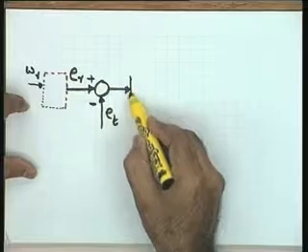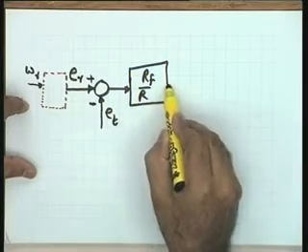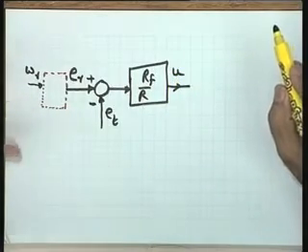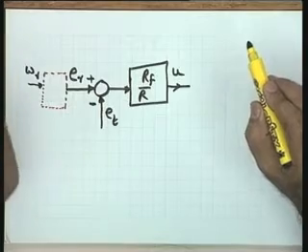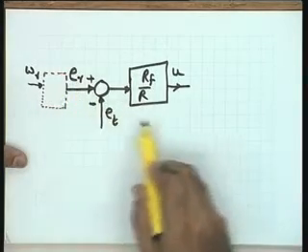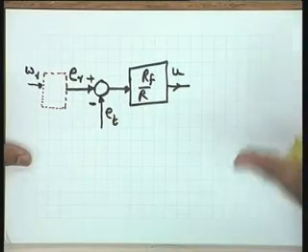So, here I am putting in this particular block an amplifier gain RF by R, and let me say that U is this control variable. So, you will please note the physical relevance, the physical equipment also which is being used to realize the various objectives. Now, U is the control signal. This is a signal which has the knowledge about the action to be taken, but it does not have the necessary power to drive the actuator. So, you will like to add power to this signal, keeping the basic intelligence at the same level.